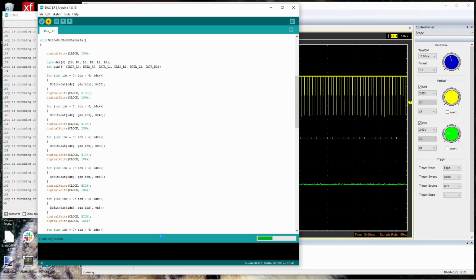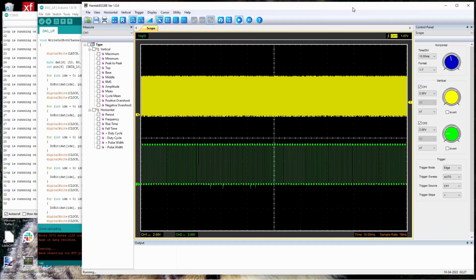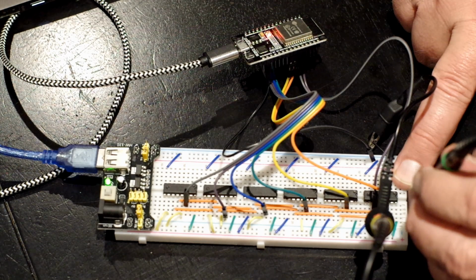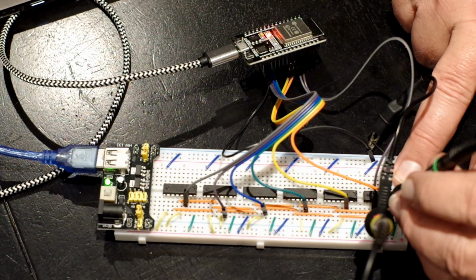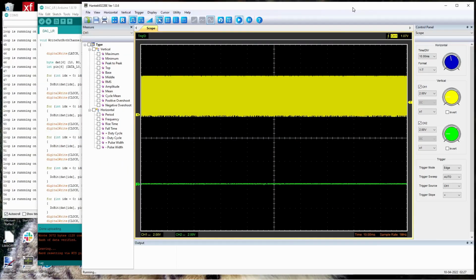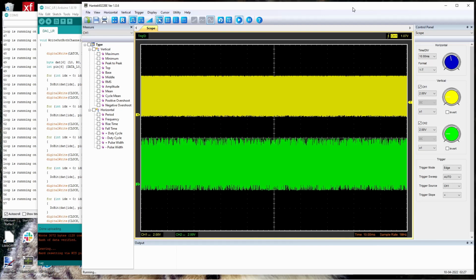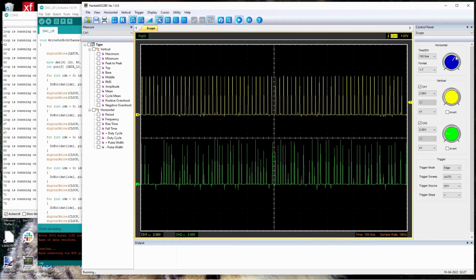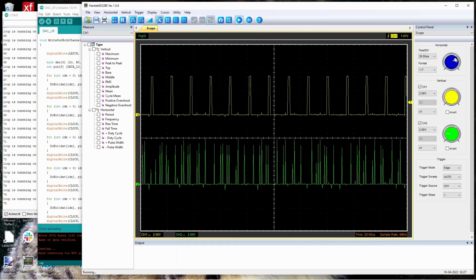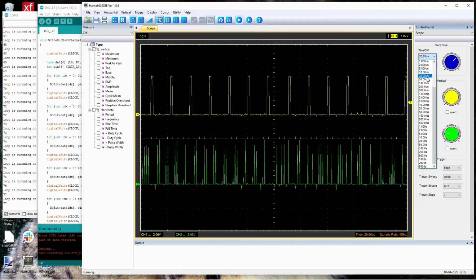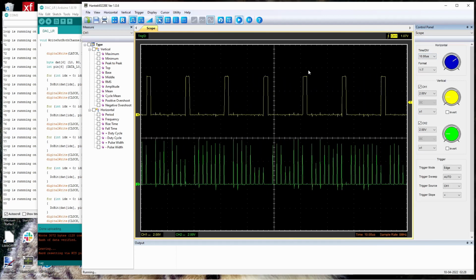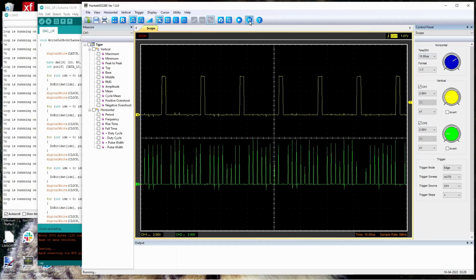Sketch is compiling right now. Okay, it's down there. Looking at the scope, green line right now is on a data pin. I'm going to put it up here on the clock. Okay. And remember, for every latch, every yellow, there's 8 clocks. So let's speed this up. So that's 20 microseconds. Let's go to 10 and pause it and see what the deal looks like.